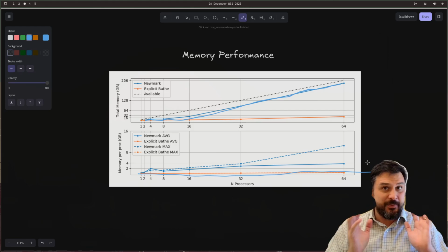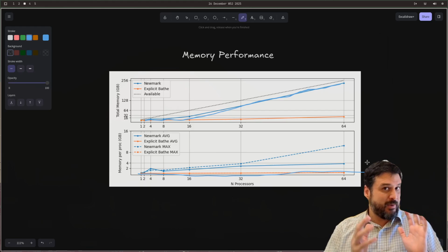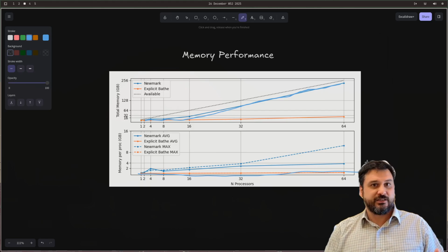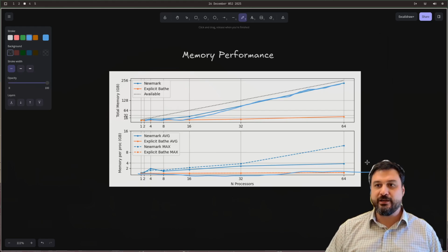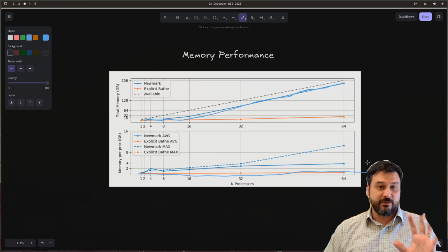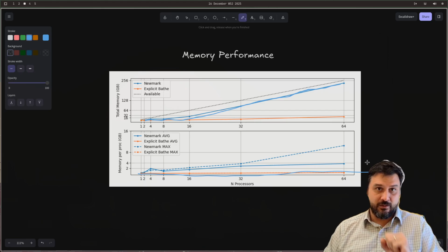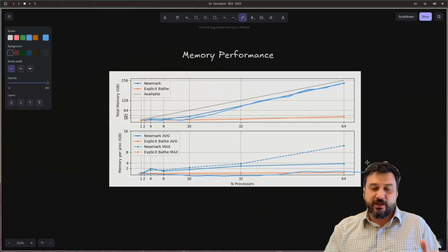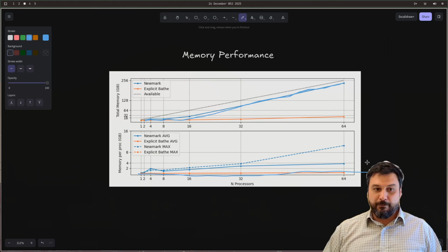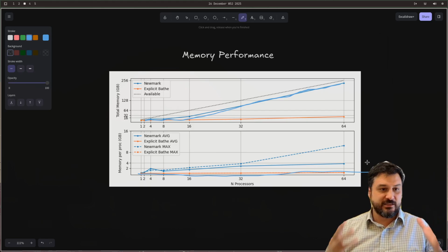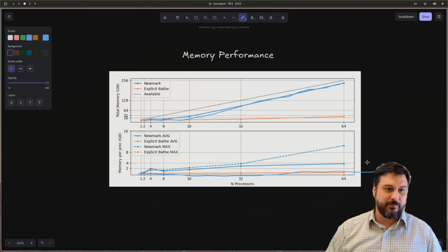Like we're in OpenSees, our memory usage is all in the system of equations. In this case, we're doing linear analysis. So if you're doing something fancier like nonlinear constitutive models, then your elements or your Gauss points are going to start storing more memory. But already your system of equations has a huge impact in the memory usage.